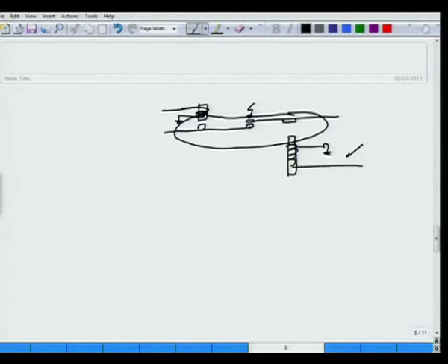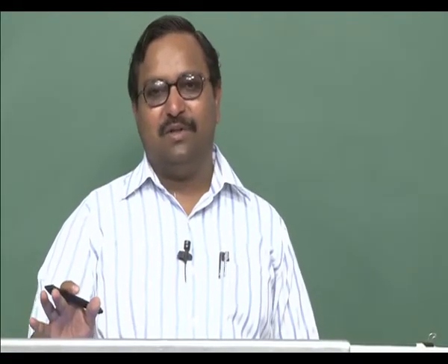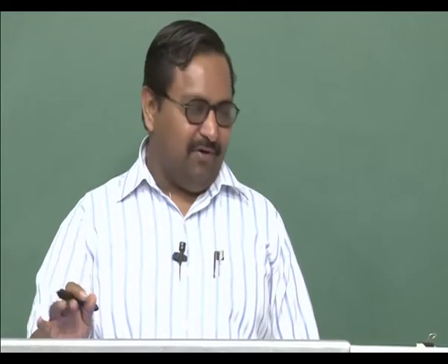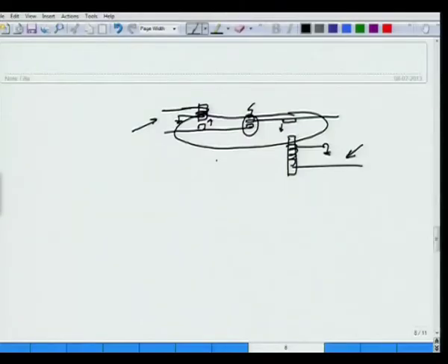Whenever you energize this electromagnet as well as this electromagnet, this will be pulled downward, this will be pulled upward, and a connection will be snapped in. The moment any one of the electromagnets is switched off, the connection will be broken and voice communication cannot take place. And we call this thing a cross point. Okay, this is a cross point, still electromagnetic, and this cross point can now be used to build the switching module, and this particular switching module which was built is known as crossbar.